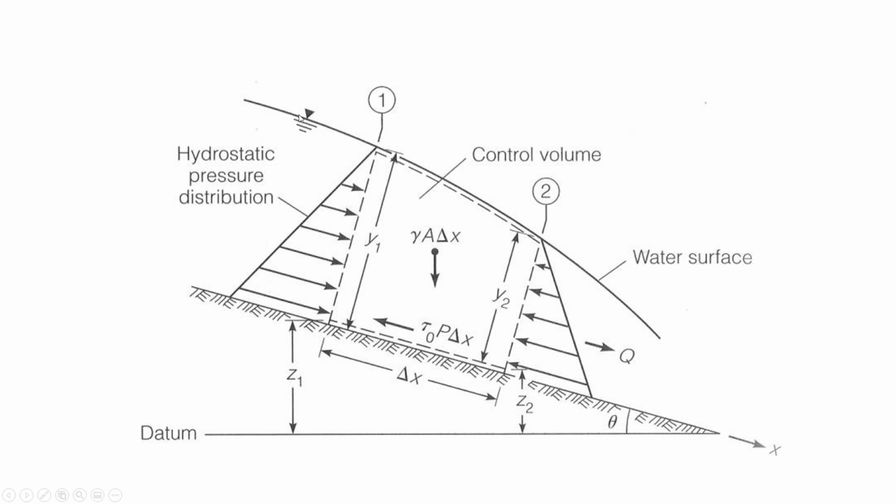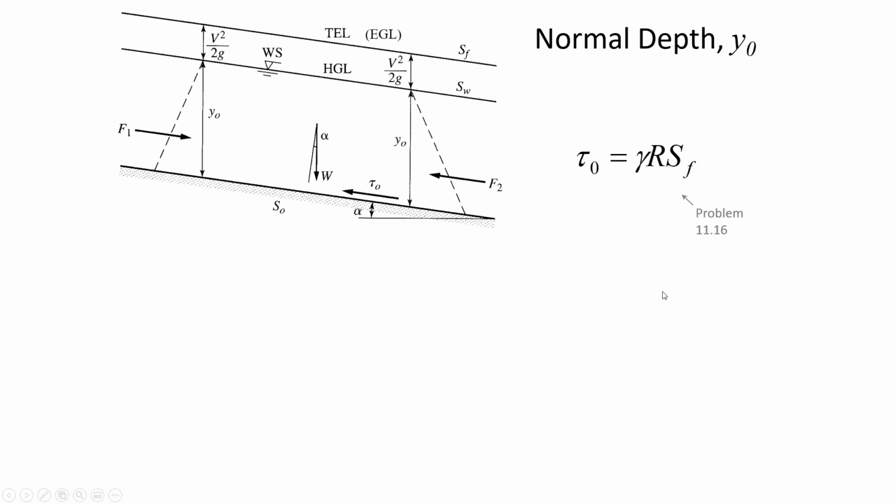They're different because the water surface slope is not parallel to the channel bed slope. And so there's something downstream, like think about water flowing over a cliff that's drawing down the water here. There would be some feature disturbing the flow to cause this non-uniformity. Whereas in this illustration, we're far enough away from any kind of obstruction that it's achieved an equilibrium so that the flow depth isn't changing.